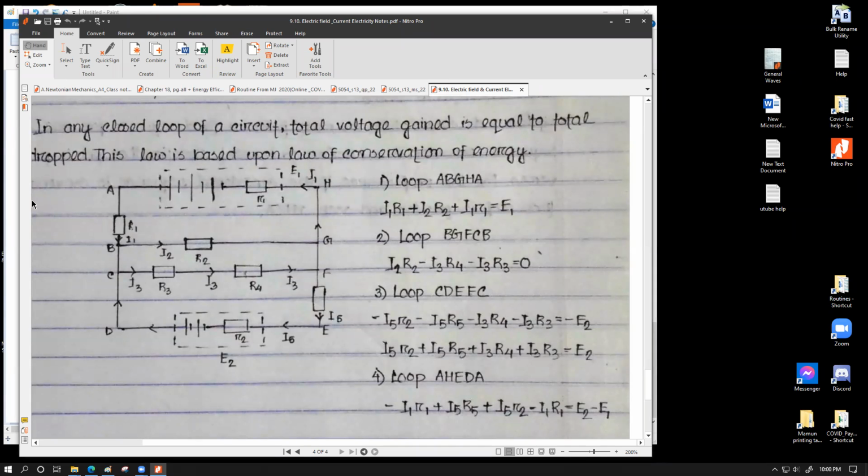So once again, first thing, if the question does not give us a specific direction of current, we have the privilege to assign the direction of those currents. Then we can go ahead and do the necessary calculation to find out the value of these currents. There are ways to calculate this. These are the equations, and I'll help you understand those. At the end of those calculations, all the answers for the currents, let's say I1, I2, I3, and I5 through this branch, would come with some number, and the calculation can also cause them to have negative numbers.